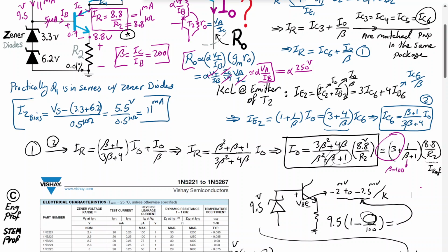So if the reference current is, let's say, 1 milliamp, the output current is 3 milliamp. The reason I say that is because the base current is the output current, 3 milliamp, divided by 200, that's the beta. So I'm going to write it here, I out divided by beta. So if we substitute, we end up with alpha times 250 divided by 3 milliamp divided by 200.